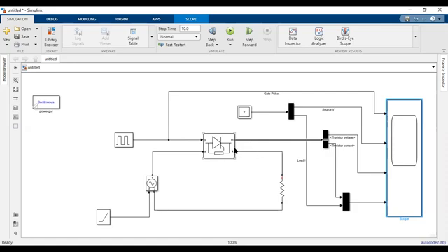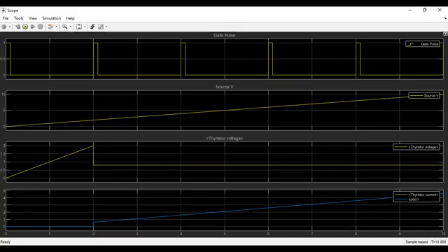that is the current out of the thyristor, or IT. IT flows directly through the load. Therefore, the thyristor current IT equals the IL, or the load current. Hence, they have basically overlapped. Therefore, you cannot see this. To avoid this sort of confusion, in the next step we will do some modifications in the given circuit so that these two currents we can see separately, so that there is no confusion of this overlap.